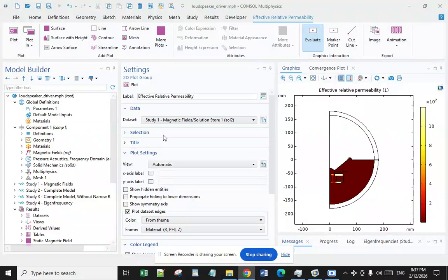As a result, more sophisticated signal processing techniques are needed to isolate signal from noise. The second challenge and disadvantage is that it is limited to metallic and/or magnetic products. NDT of plastic and ceramic material is not suitable, or at least not convenient, using electromagnetic acoustic transducers.